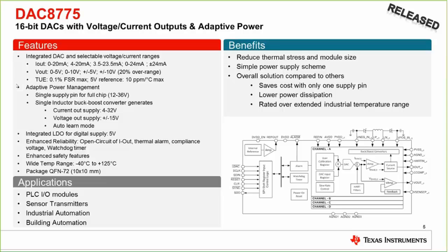The next question is, how fast can the DAC be changed over its full range of 16 bits? So that relates to the previous point as well. It depends if you were talking about something in full tracking mode or in one of the clamped modes. I think if you were to go from the full-scale range of plus minus 24 milliamps for the current output, this is the worst case. It takes about 2 microseconds to slew from minus 24 to plus 24. If you were doing one of the unipolar ranges, something closer to 1 microsecond, which is also true for the